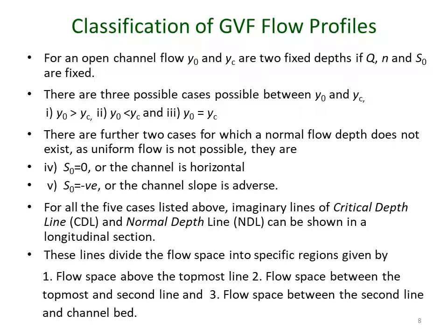For an open channel flow, Y0 and YC, that is the normal flow depth and the critical flow depth, are two fixed flow depths if we consider that the discharge, the Manning's roughness coefficient and channel bottom slope are constant or fixed. So given that this statement is correct, there are three cases possible here between Y0 and YC, and those are